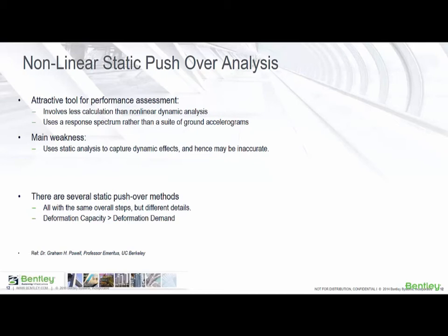Pushover analysis identifies limit states that cause damage leading to collapse. The method is thus quite suitable for structural design. The main weakness of pushover analysis is that it uses static analysis to capture dynamic effects and as such may be inaccurate. There are several pushover analysis methods in use. All of them, however, have the same overall steps but different details. They are all driven by the same strategy of providing deformation capacity larger than demand.